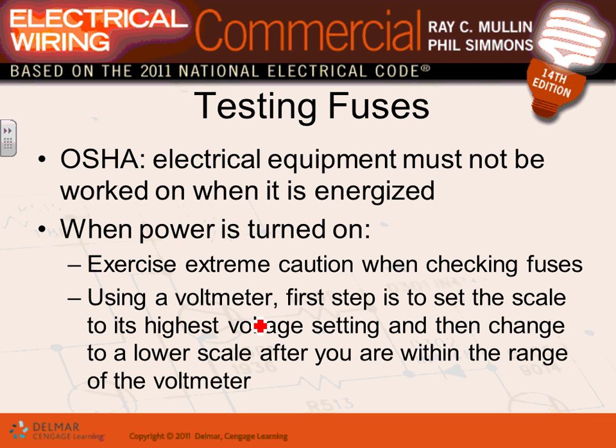If you want to check the fuse hot, you put the voltmeter right across the line side and the load side of the fuse. If the voltage is close to zero, then the fuse is good. If there's a voltage across them, then this fuse is burned.